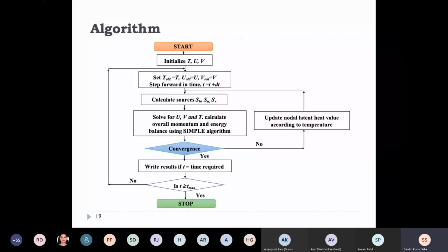There you have to be a little careful in setting the time step, because you have time in your hand to converge the solution. You may not be able to use 0.1 second; rather you have to use something like 0.01 second, only during the initiation of melting. If you do that, the whole melting process will be good. Otherwise you will have some trouble at the beginning of the melting process.